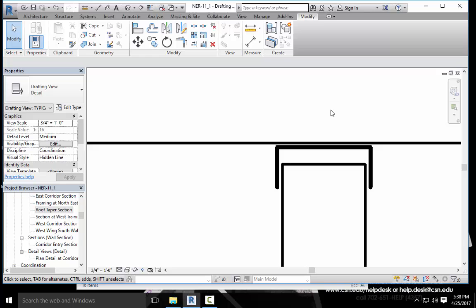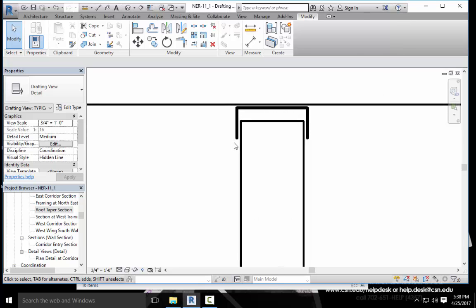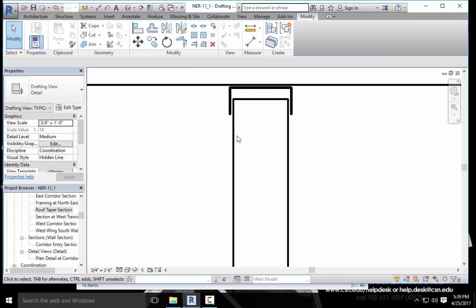And in reality, I don't know if that's the best way to draw it, but that's actually all sorts of incorrect. The detail in the book shows the gypsum board on the inside. It really should be on the outside. There should be a contractor shaking his head in the back. So let's draw the detail the proper way, even though the book doesn't look this way. This would be a metal stud and this would be a metal track. It would be in place before you put the gypsum board up.